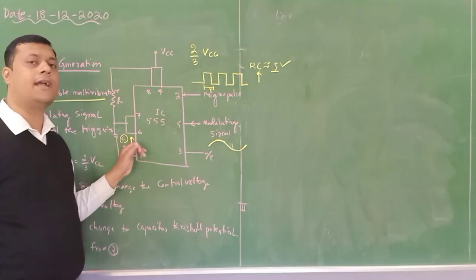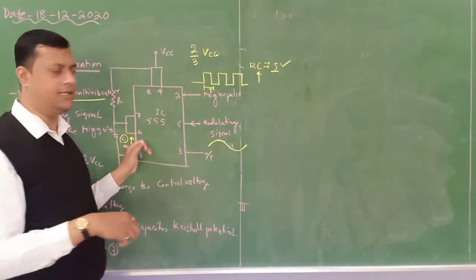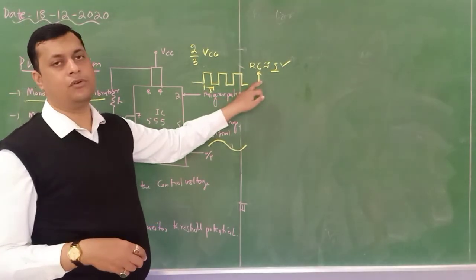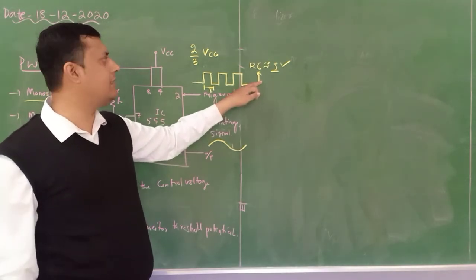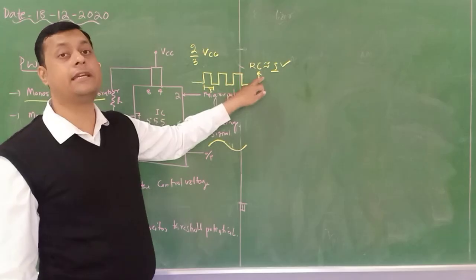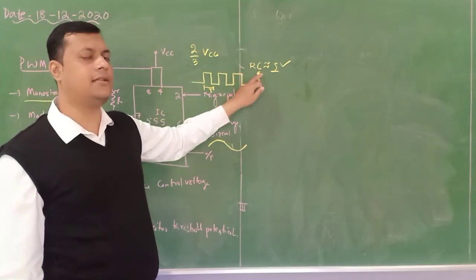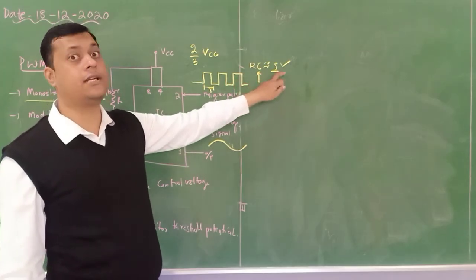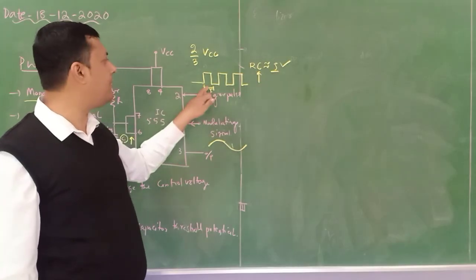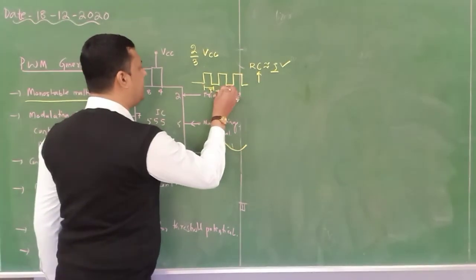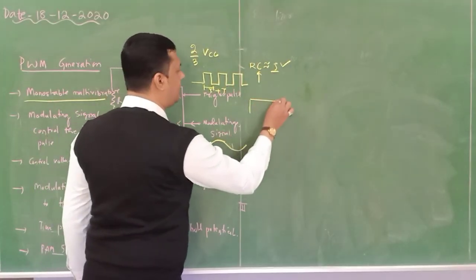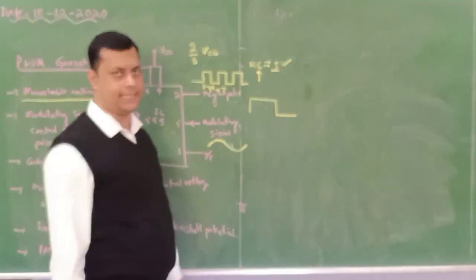So it will identify the maximum potential, due to which the capacitive value will increase, and so your RC value will increase. If the RC value increases, your time constant tau increases, so the pulse width increases. So if it is T, it will become T plus tau, so the time period of that particular pulse will increase like this.